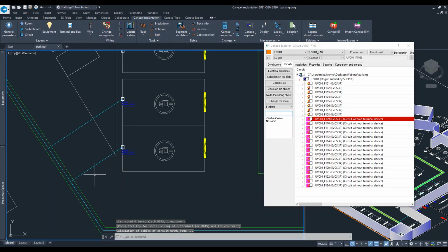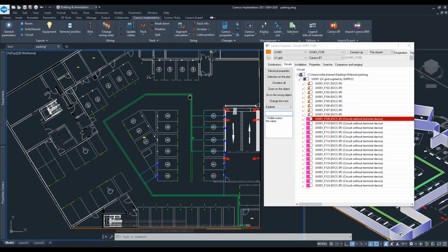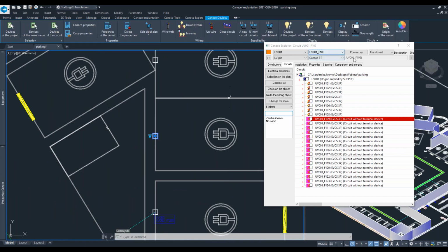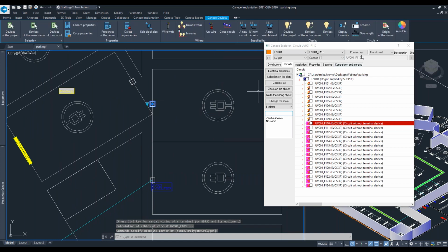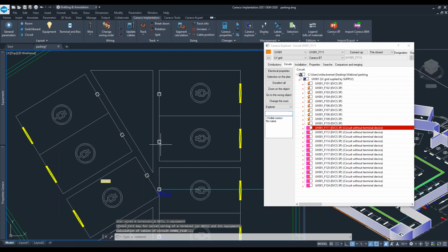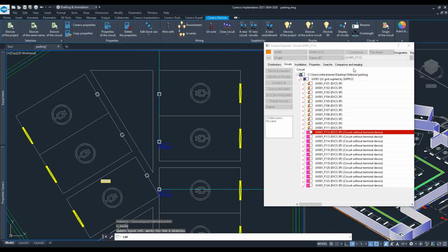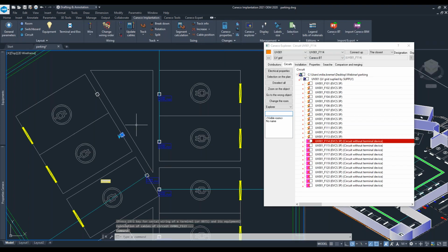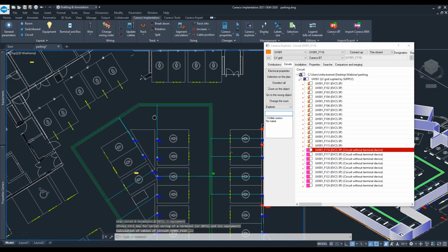For sure, the cable tray which I placed is just an idea. It's maybe not the best way because it should also be connected here to have all the cable routing correct. But it's up to you to define the cable way. Whether it's a cable tray or a different type of cable way, you are free to define it. The cable routing uses the shortest way between the device and the defined cable way every time. So you see a different way every time, because it chooses the shortest way between this device and the